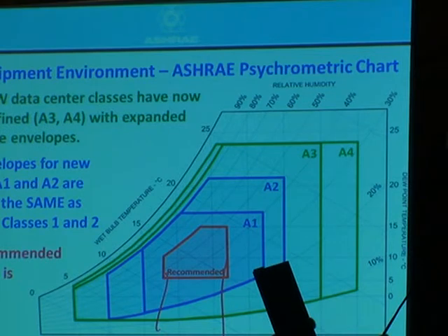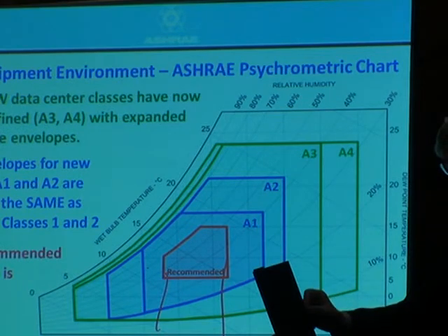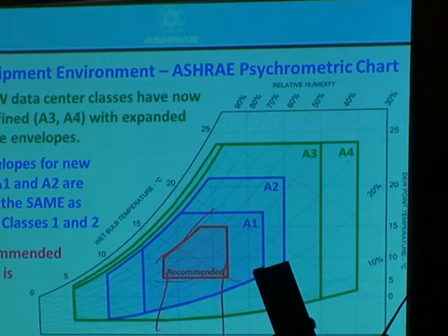And then we have humidity requirements. We have it basically at a dew point here, a dew point here, and an RH of 60%. We tried to make it a rectangle, but we weren't able to at 60%, because with printed circuit cards, if you go above 60% for long periods of time, they will have some filament growth, which will cause them to short out.